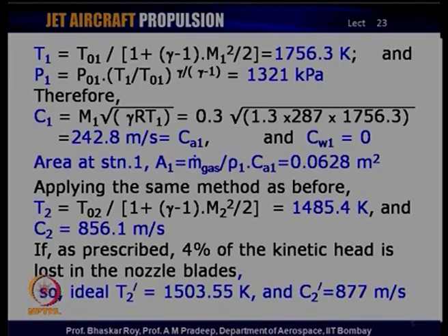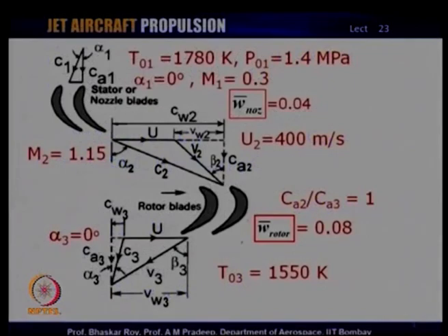So, if you keep your eye on the velocity triangle, you would see that we are trying to solve all the parameters that are shown in the velocity triangle as far as possible. The trick of solving such problems is that if you can find all the parameters shown in this velocity triangle, you would be able to calculate the performance of the turbine completely and fully. So, one of the things that you may like to do while solving a problem is to compute all the parameters that are shown in this velocity triangle.